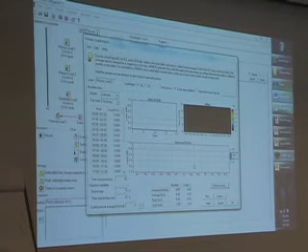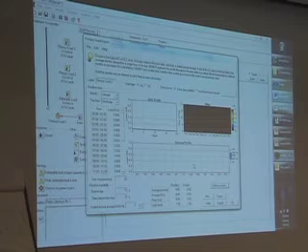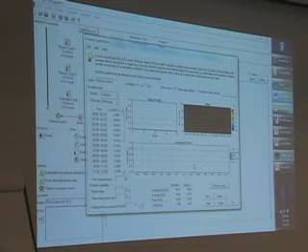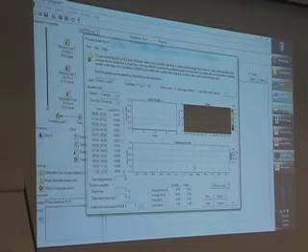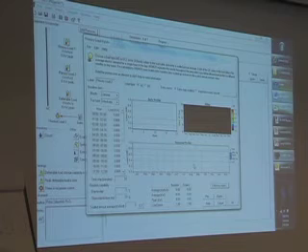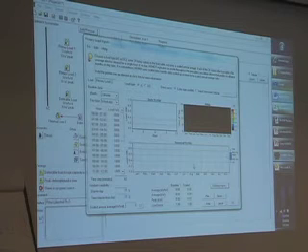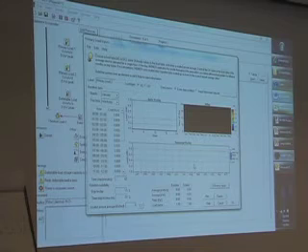For example, if the efficiency measure only applied to the lighting load, we might define one of the two primary loads as the lighting load, and then apply the efficiency measure to it, which is going to be a lot bigger in the winter than the summer, and it's going to have a different daily shape, etc. And then the rest of the load doesn't get the efficiency measure. So that's one piece of our load management capability.